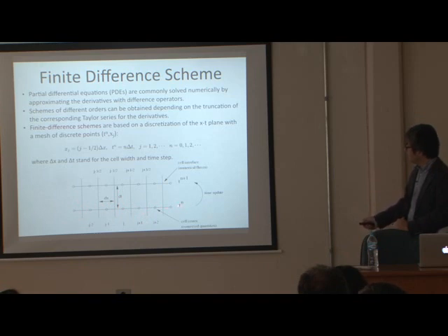So t equals n time. And then if time is updated, this is t equals n+1 level. We also sometimes talk about this being the cell-centered point. And the cell boundary point, or cell interface point, we say is j plus half or j minus half point. So this is cell-centered. The conserved quantity is usually put onto this point. Then after that, we may also calculate the numerical flux at this cell interface point.